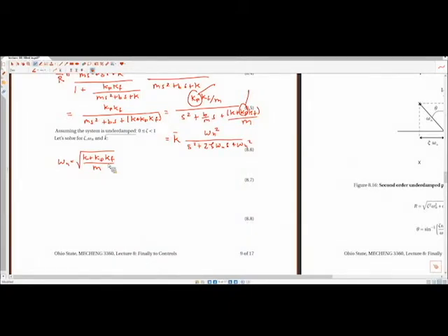Thermal systems are where you see it the most. Thermal systems like the room, the time constant of this room is very, very slow. If I were to light a fire in that corner of this room, someone on the other side of the room wouldn't feel it for a long period of time. So thermal systems are often overdamped, but for fluidic systems, mechanical systems, and electrical systems, you're almost always going to be underdamped. So this is a generic case that wouldn't apply to everything, but it applies to most of the cases we'll see. All right, thanks for that question.